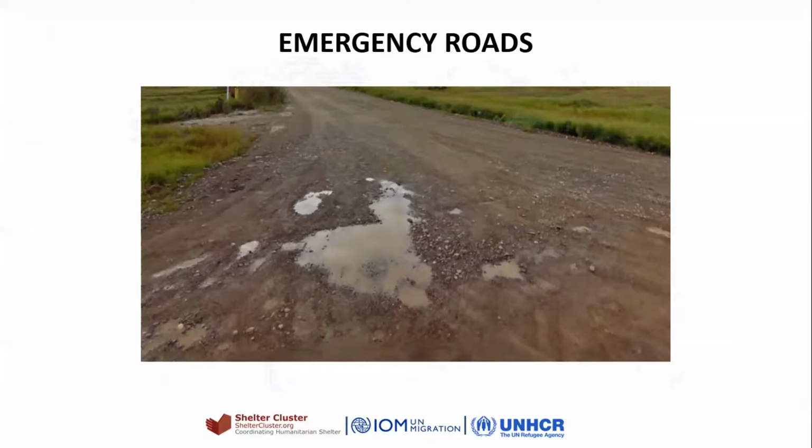After the light survey, we explore the situation and we either compact the existing road if it's only soil, or we backfill lightly the existing route we are going to choose, joining the main artery. We want to join the main artery with the location of the settlement, the spontaneous settlement, or the camp.